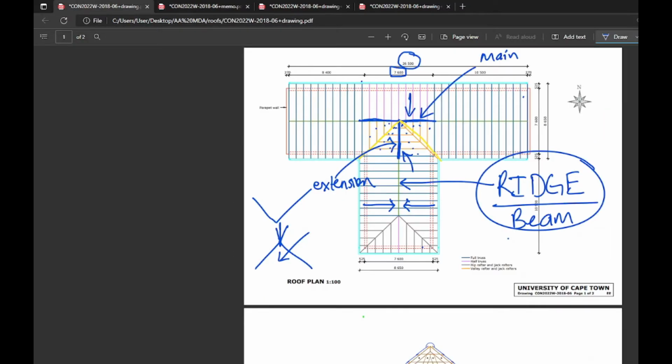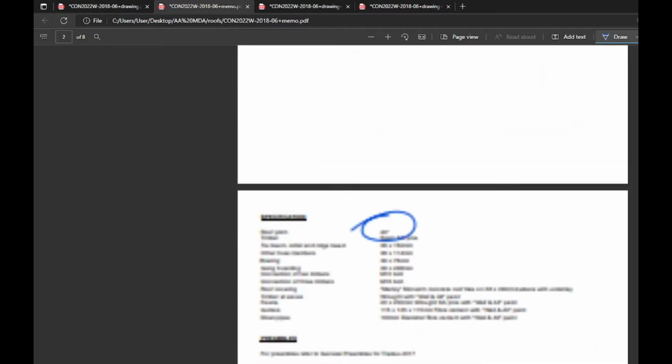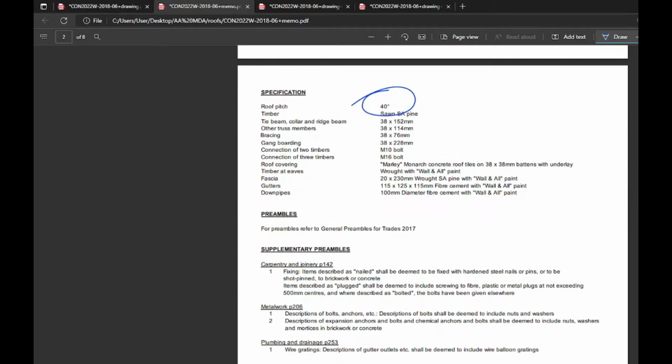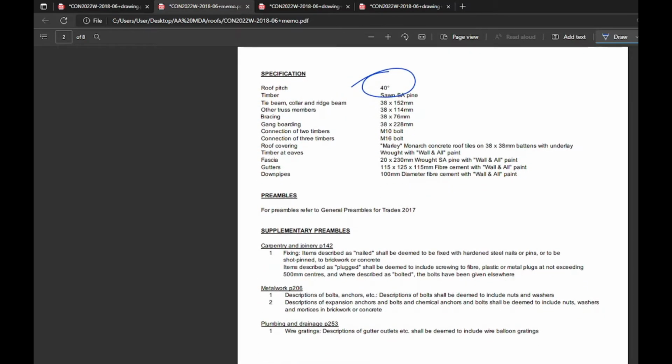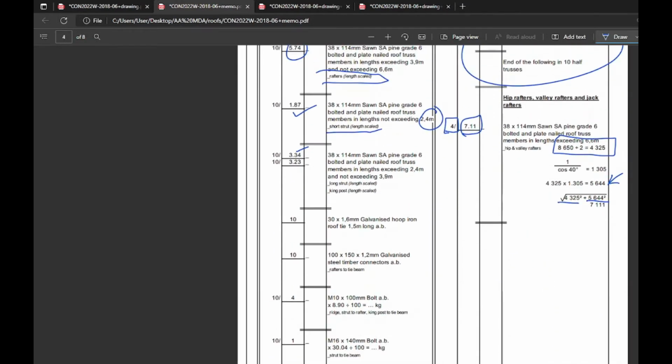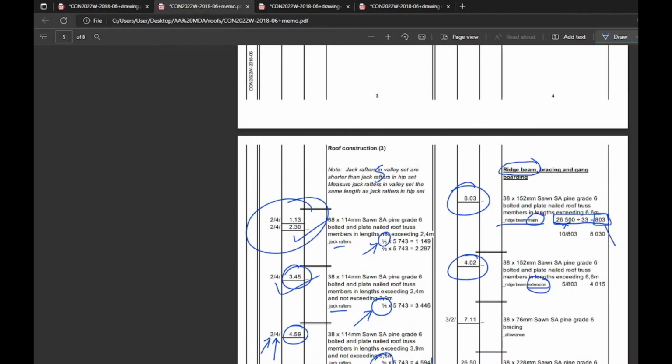So what we are actually saying, and I'm going to take a look now, is that it is speaking to the center-to-center span of each truss. Let's take a look. If it's given, it's not. No. Okay, so what you've essentially calculated is the span from one truss to the other, and since it's actually inside to inside, it is 803. So if you wanted to calculate center to center, that would actually be possible.